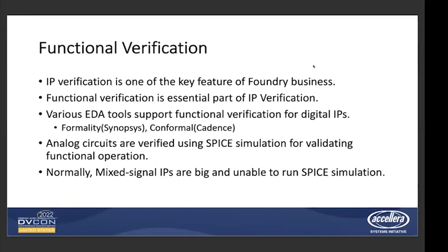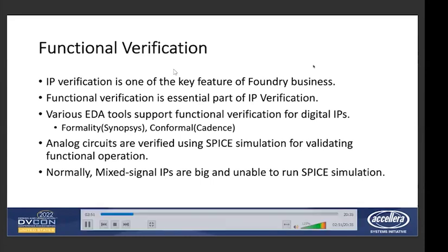For digital IPs, several commercial tools support functional verification, such as Synopsys Formality or Cadence Conformal. However, there is no golden solution for analog circuit verification or mixed signal IPs without SPICE simulation.